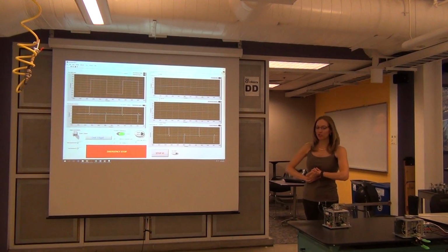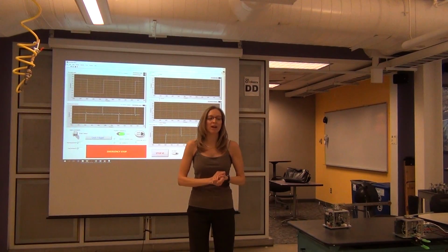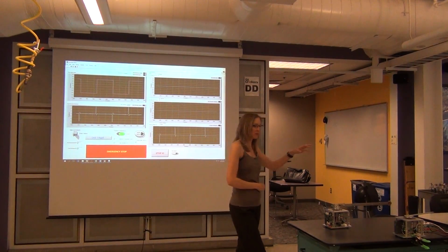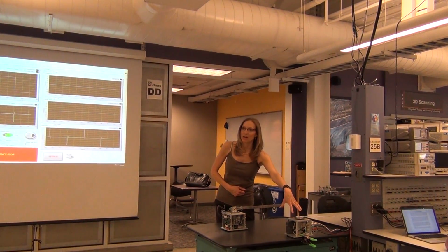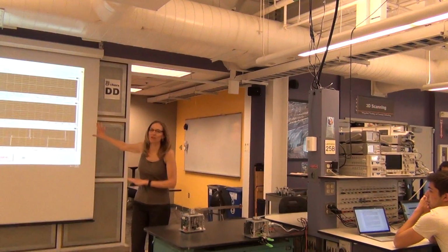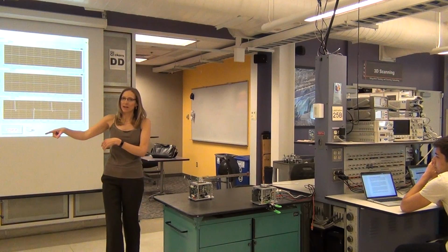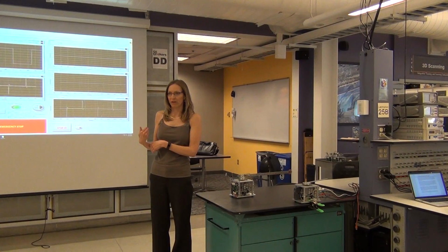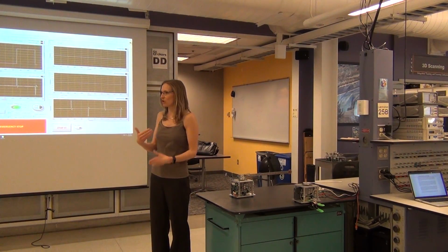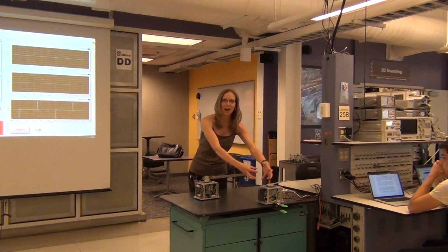Another thing I want to mention to you is the control system is not being run in LabVIEW. The control system is being run on the MyRio, which is local to the spacecraft. So imagine the computer and the LabVIEW interface is just your ground station. Your ground station is sending position commands and then reading back the performance position of what actually occurred. But it's not doing any of the implementation of the control gains, and all of that math is not happening on the ground station. It's happening on the spacecraft.